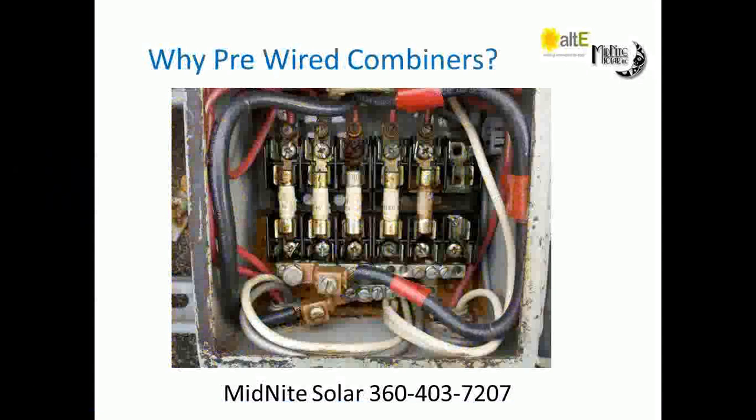So then you can take the Magnum 4024 pre-wired system. You take 2 strings of the N phase and move them over to the Magnum and leave the 3rd string on the utility grid, and you're good to go. Now, if that had been a 6 kW Fronius inverter, for instance, you wouldn't be able to put that on a Magnum 4 kW system, so you would need a 6 kW battery-based inverter.